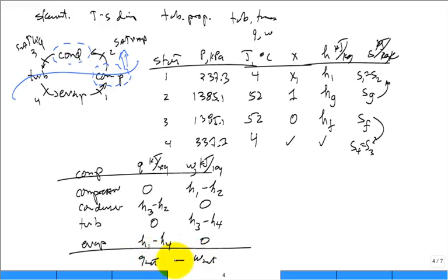And when you do the net, if you do the sum of the Q's, Q net, and work net, guess what? They need to equal. If they don't, you have an error. Look for your error. All right. Then you can answer the questions.